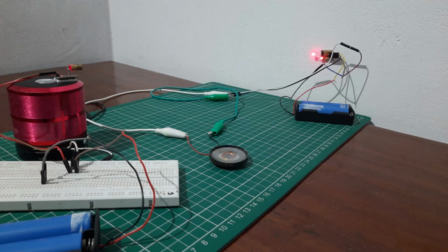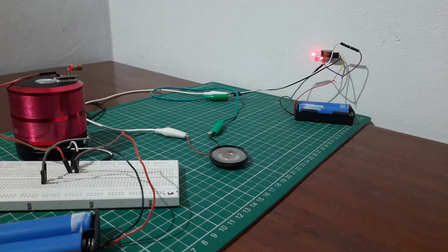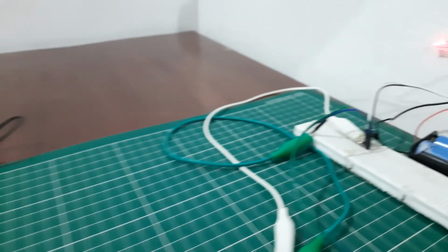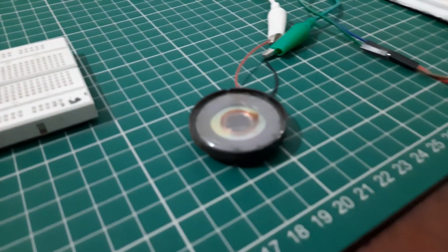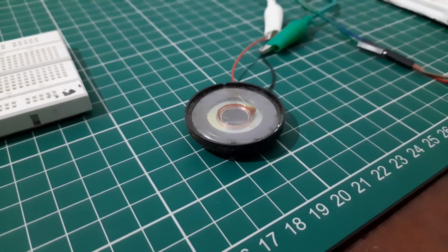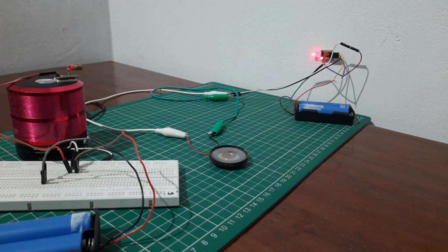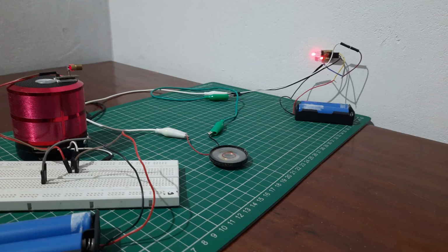But it is not enough. Now connect a 5 volt source to the 5 volt and ground pin of the sensor. Now we can hear the audio. But still the volume is not up to the level and is full of unwanted noises. So I have used the same BC547 transistor amplifier to increase the volume. Now we get acceptable performance.